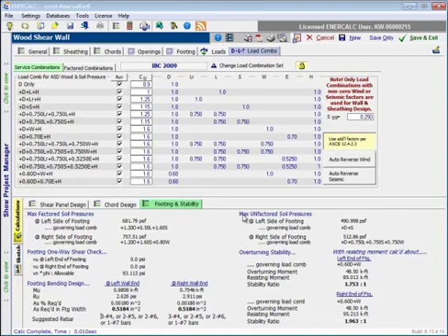Upper right hand side, we now come to the maximum unfactored soil pressures. So here we're getting into a service level soil pressure that's meaningful to compare to a geotechnical report, and we can see results reported at both the left end of the footing and at the right end of the footing, each with its governing load combination, the load combo that's responsible for producing this soil bearing pressure.